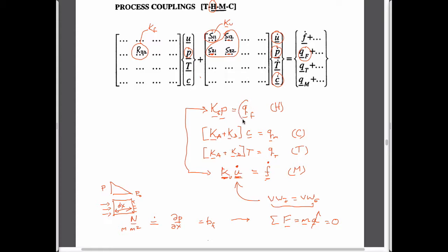These are written in terms of a volume rate of change. So in the same way as these are forces that are applied here, or perhaps rates of changes of forces, then a volume flux is the balance that we have on here. So we're conserving volumes. And so the effect of the linkage between this is that if you apply a displacement to the structure that will act through this term here, then in the equation for flow, which is this one here, it has to affect the mass balance. And so if you squeeze it by some amount by displacing it, by straining it, you physically will push fluid out of the system. And so you're balancing fluxes.